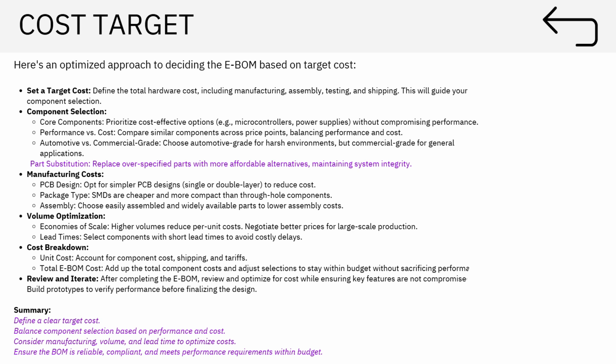So you have to be very careful about what exactly you are planning, and things will come with experience. You can refer to a few open source designs from SparkFun, Adafruit, whatever you can find online, to understand how things are done. I think Adafruit has their projects on EagleCAD, where you can just go and see how all the routing has been done, and how many parts have been placed on the top layer or the bottom layer. Those things you can go and check.